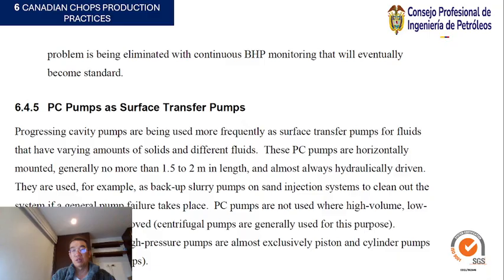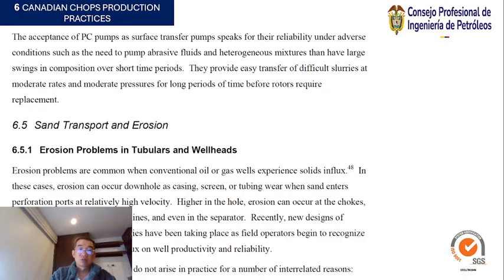PC pumps are not used where high volume, low pressure fluids are to be moved. Centrifugal pumps are generally used for this purpose. Similarly, high volume, high pressure pumps are almost exclusively piston and cylinder pumps, triplex or quadruplex pumps.